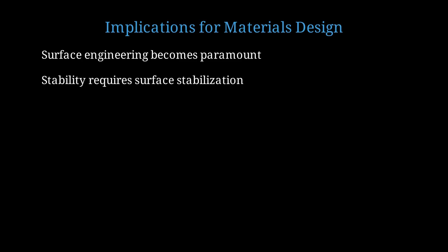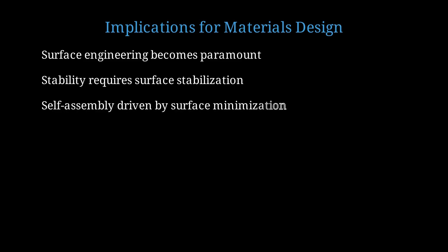Let's discuss the profound implications for materials design and nanotechnology. In the nanoscale regime, surface engineering becomes more important than bulk composition. Coating, passivation, and surface functionalization dominate material properties. Nanoparticle stability requires surface stabilization through ligands, surfactants, or oxide shells to counteract the destabilizing surface energy. Many self-assembly processes are driven by the system's attempt to minimize total surface area, leading to structures like micelles and vesicles. Precise size control in nanoparticle synthesis is critical because properties change dramatically over just a few nanometers due to surface dominance.